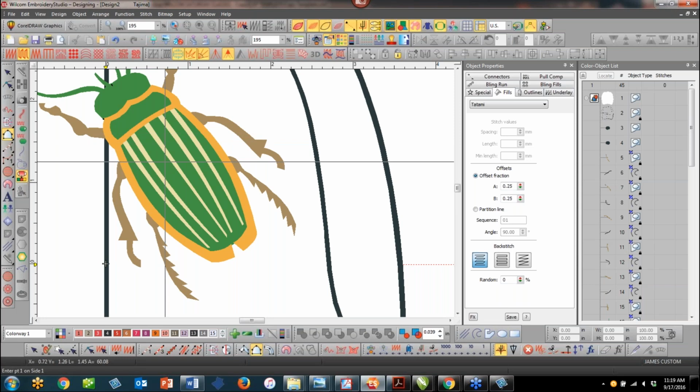There's a space here, so I need to have something laying down on the fabric that's not going to create a trim. If I digitize this first and then digitize this leg, there's going to be a trim underneath, unless I go in and create something in order to keep the needle on the fabric for as long as possible.